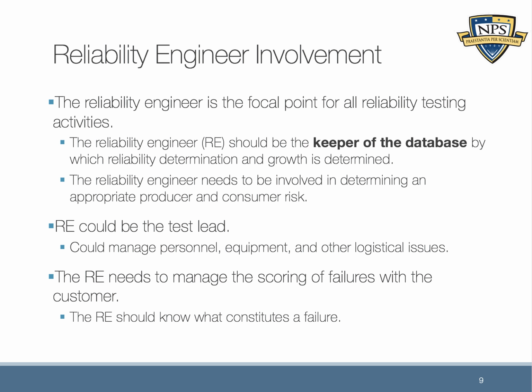you can actually avoid holding up your test. You usually still have to do a FRACAS process, but it won't hold up your test, because you can say before you start the test that if these things occur, then we're going to do a FRACAS process, but they're not related to this particular test, so we're going to continue. And usually that's a very acceptable thing. So the point here is that before you start a test, you really want to understand what constitutes a failure and also what does not constitute a failure.